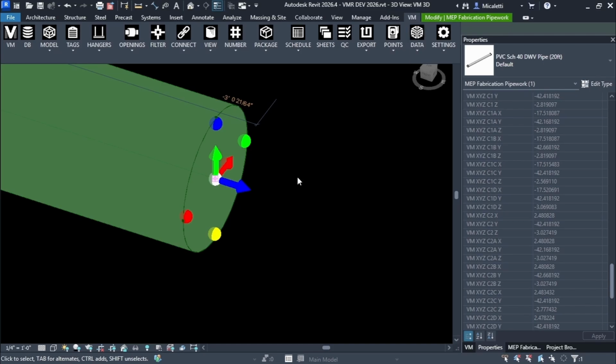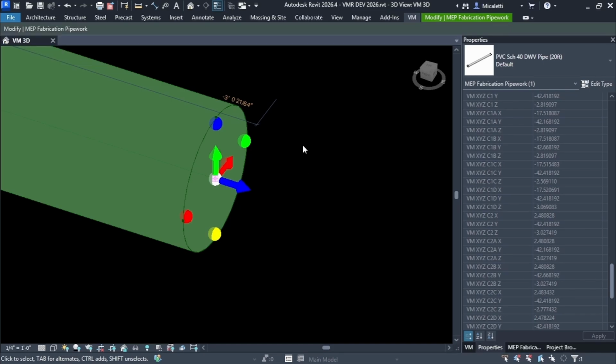Yeah, that's kind of a funny thing I do with our setup. There are projects where they want us in shared coordinates, but it'll just be the architect's arbitrary shared coordinates. So we sort of have to put our base point and set our project up in these useless shared coordinates. So then I always have to put the survey point in the actual real world survey coordinates, and that's what my field team likes to use.